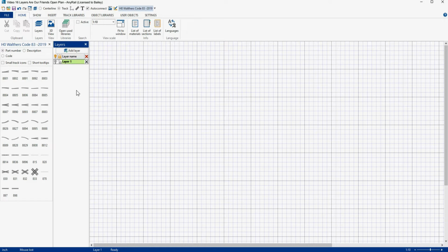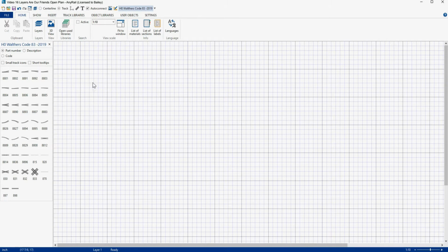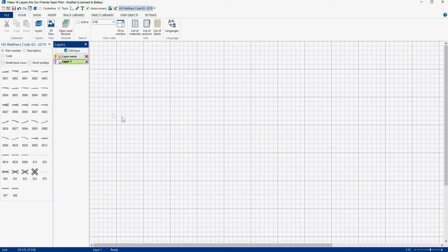Now, most of the time when you're drawing in CAD, you don't really need to have the layers panel visible, and it does take up drawing space. So when you don't need that panel, just go up and click the X and it goes away and you get that drawing space back. And when you need it, just right-click, hit layers, and it will come back, and then you'll be able to change layers, which we'll show you in a moment.